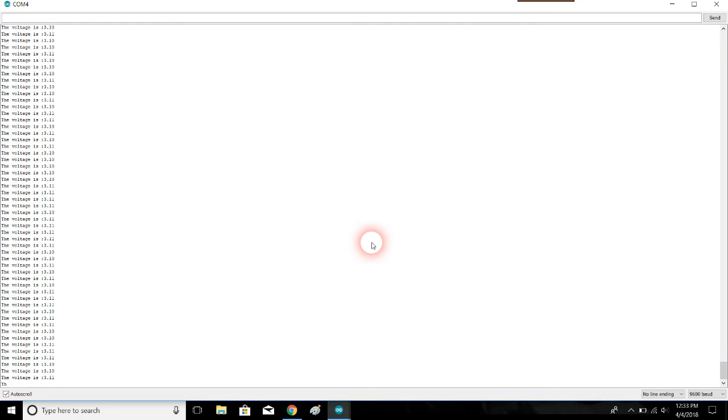Just because the resistor says that it's 10,000 ohms doesn't necessarily mean it's exactly 10,000 ohms. It probably lies very close to 10,000 ohms, within like 5% or so. The same is true of the 4.7 thousand ohm resistor as well. Since they're off by a little bit, our reading is a bit off as well. But there you go, we finally got there.